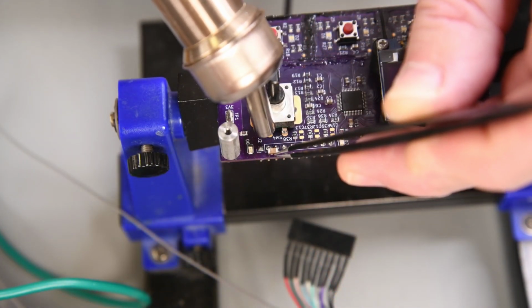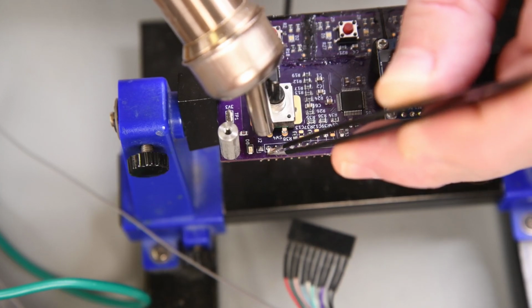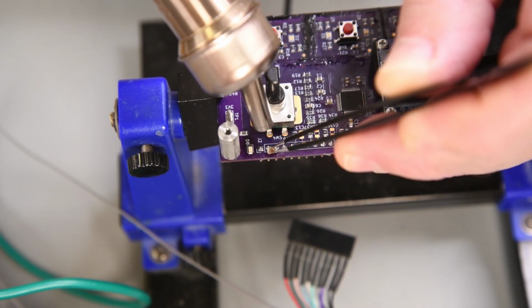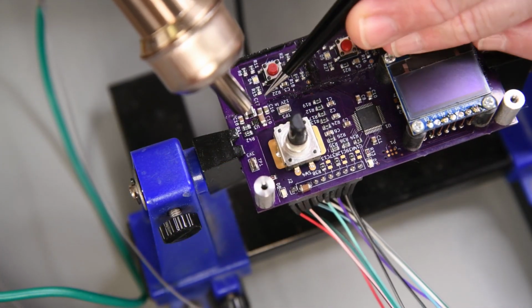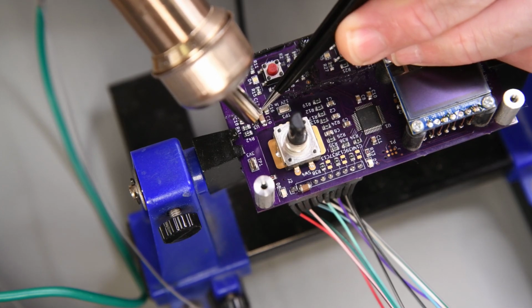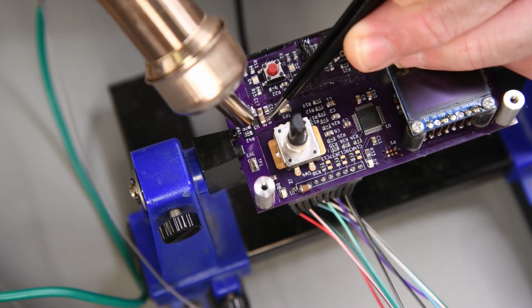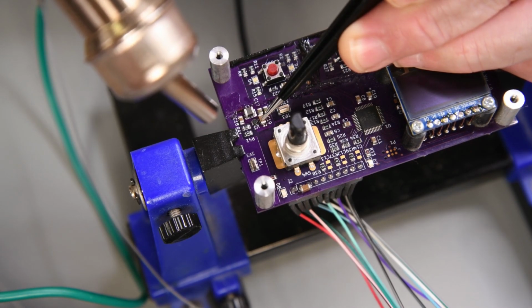I'm going to put one across the power pins feeding the board. I think that will be okay. Being soldered to the pins and not on a pad may be a bit too much stress in the long run. And I will replace the C19 cap with the 1206 case capacitor. 805s just look tiny compared to the 1206s. At least I could get it to share a pad with the other capacitors.